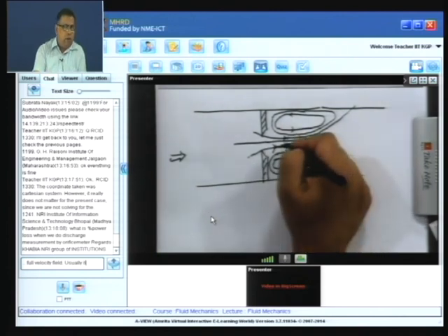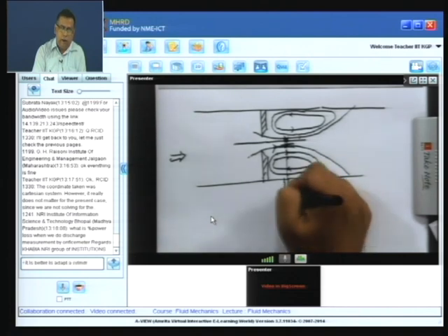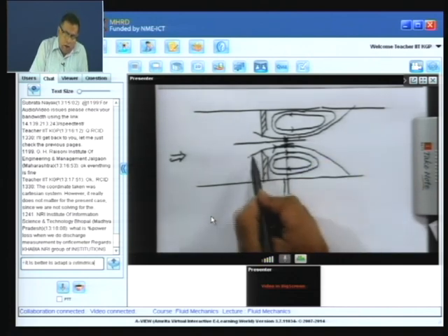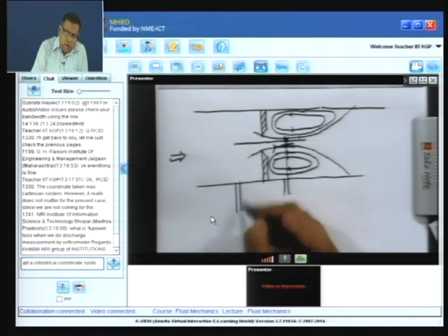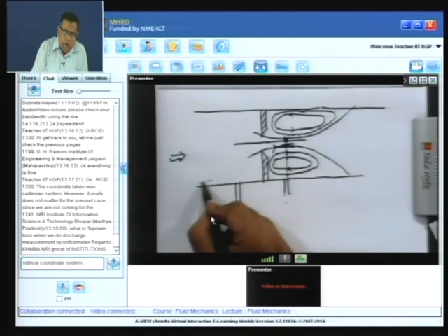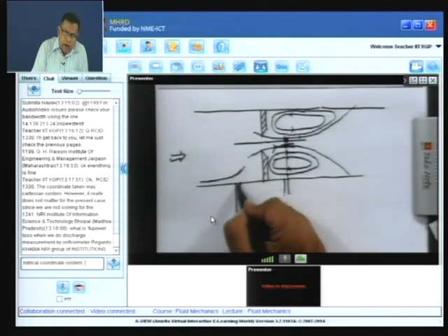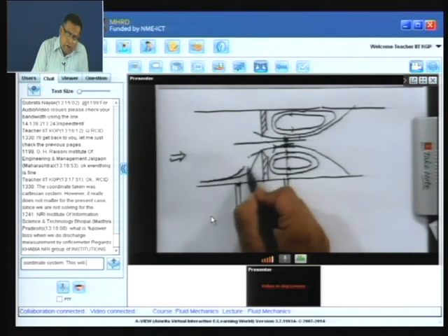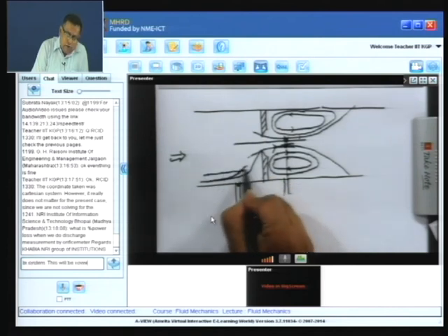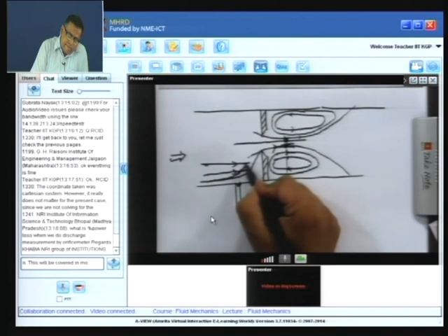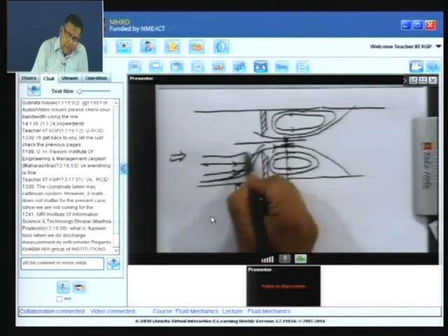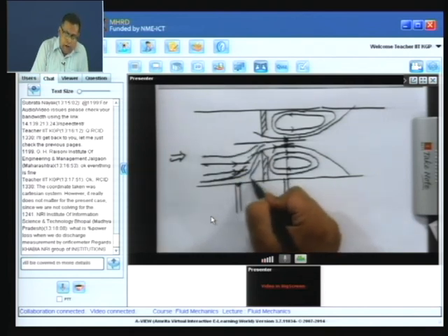Now, if the streamlines are almost horizontal lines over here, then you can apply the hydrostatic formula when you want to find the pressure difference between this point and a point inside the manometer tube. So, you would like to connect the pressure tap here also at a point where the streamlines are almost horizontal. So, you may have a recirculating zone over here also.